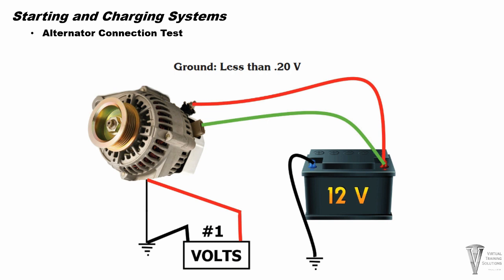Never condemn an alternator and/or voltage regulator until you have pinpointed and repaired these causes of any excessive voltage drops. Perform all three tests with the engine running. Turn on as many accessories as practically possible. First, connect the voltmeter between the negative battery terminal and the rear alternator housing. A good working limit is 0.2 volts or less.